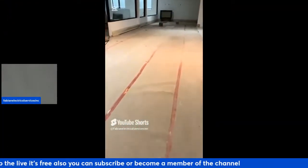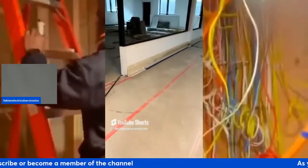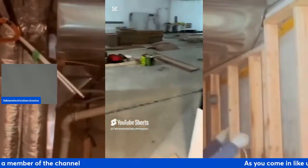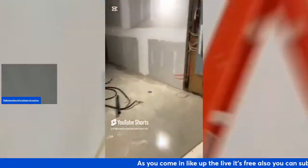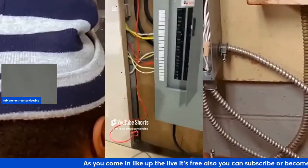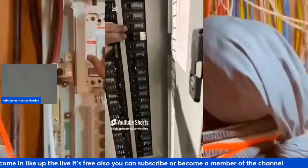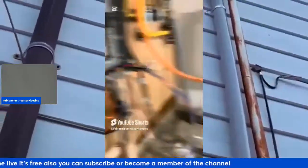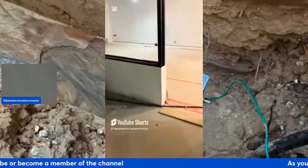we have to put arc fault protection throughout the home on most circuits, except for your kitchen 20 amp countertop receptacles and so on. Your fridge doesn't call for one. Dishwasher is basically a straight connection.